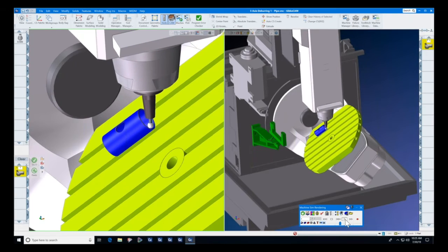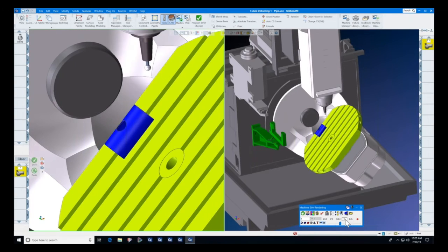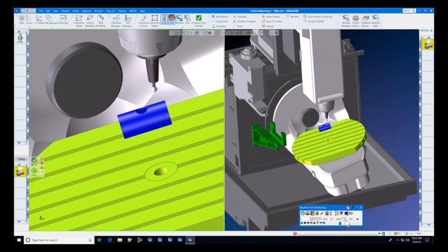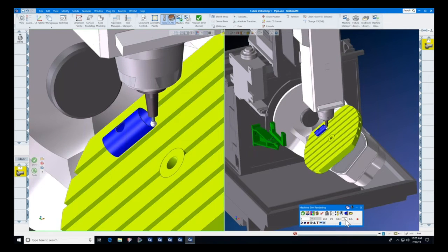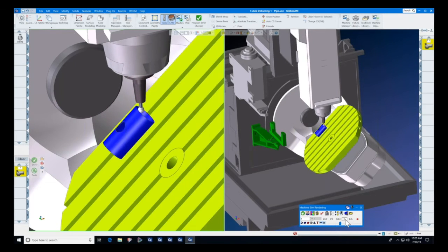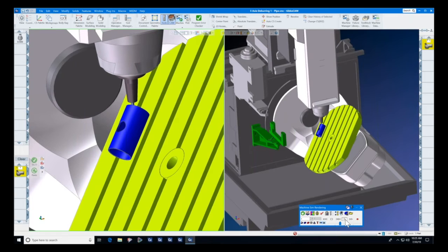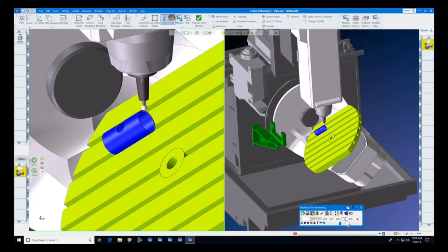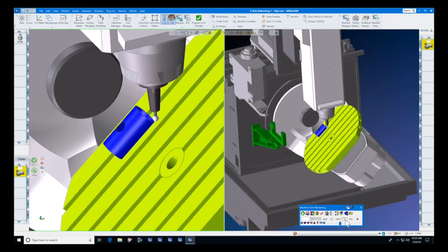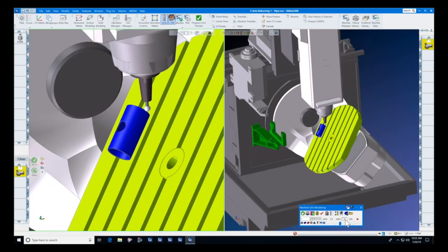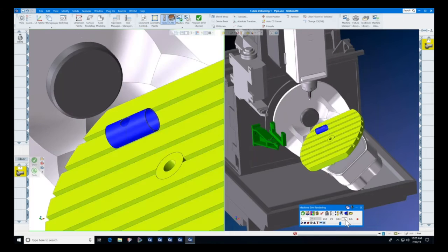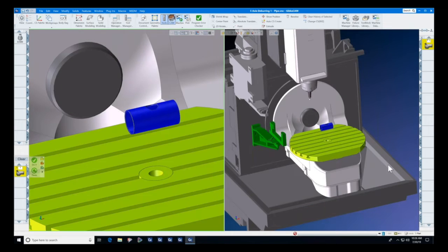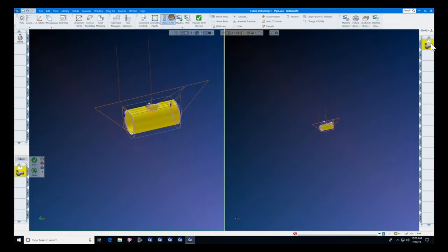It can be a grinding wheel. It could be a carbide burr. It could be a purpose-built, even a resinoid bonded rubber type tool that you would use for deburring, which allows you to use a little bit more tool pressure and give you a little bit better finish. But this deburring package is nearly fully automatic. Basically, all you have to do is point at the part and say, okay, machine this part. So let's look at how we process this.